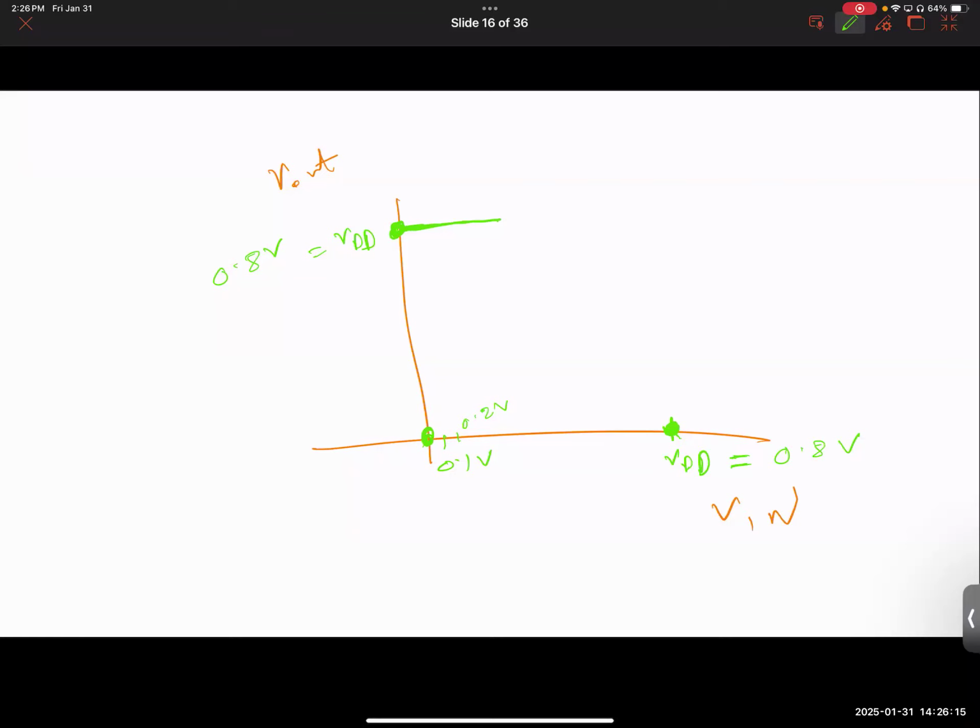And so on. How long, logically, would you continue treating that level to be lower? Logically. Yes, at least, if you are fair, at least up to VDD over 2, which is 0.4. As long as you don't cross that limit, anything that's below half of VDD should be treated as low input, and you should be creating high output.